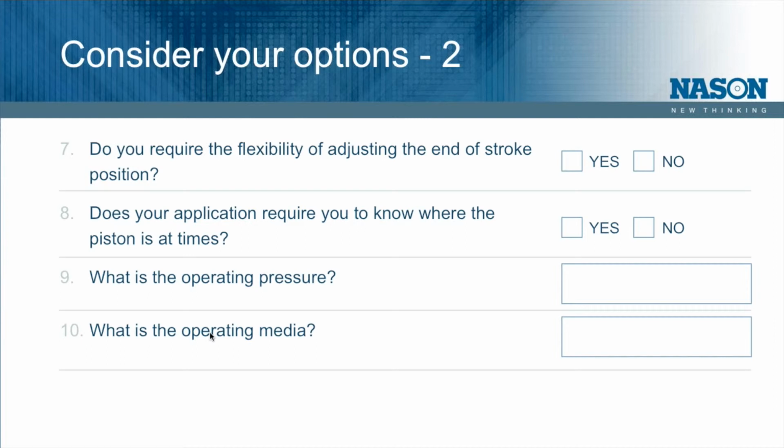What is the operating pressure? What is the operating media? Air, hydraulic, water, brake fluid? What are you running through the cylinder? Answering these simple questions will allow you to determine whether your design will be better served by a standard or an application-specific component.